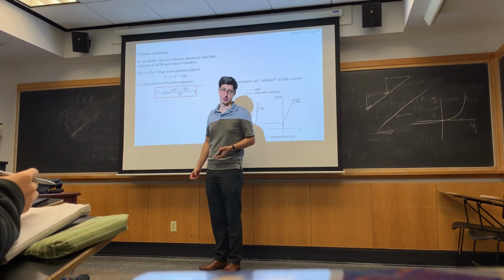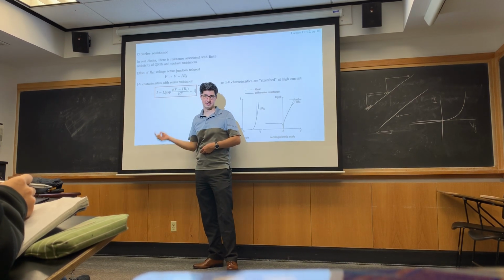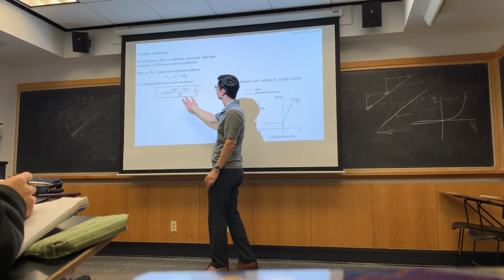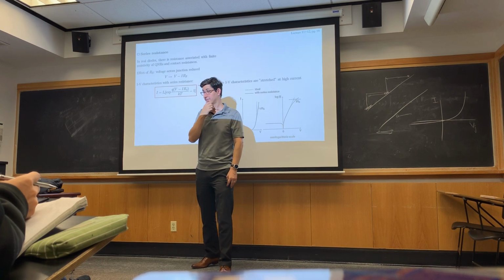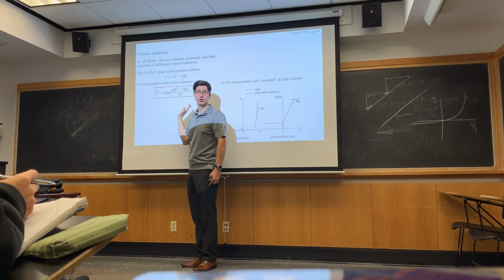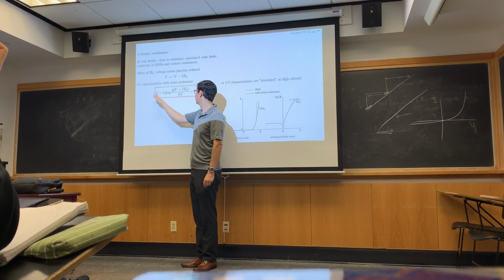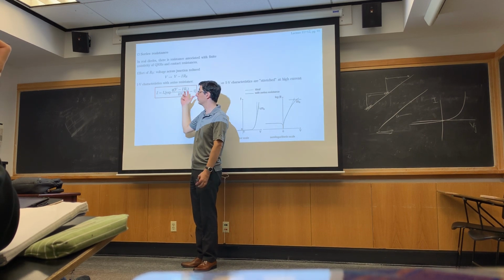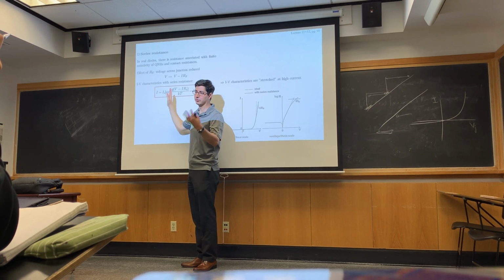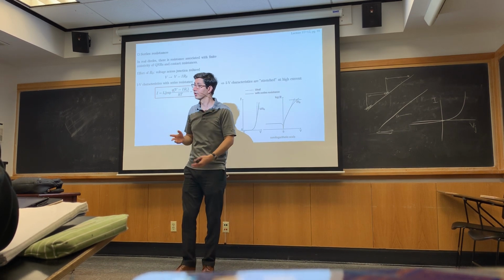So you can look for intersections. You can plot this half and then this half for a constant I, and see where they intersect. That's the voltage that you have to apply. You say, what voltage do I have to apply to get 1 milliamp out of this device? Well, you know everything except the voltage. But if you know the current, then you can just plug it in, and then you only have one variable and you can solve it.